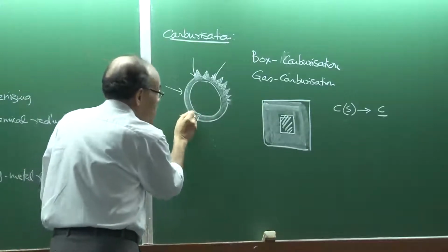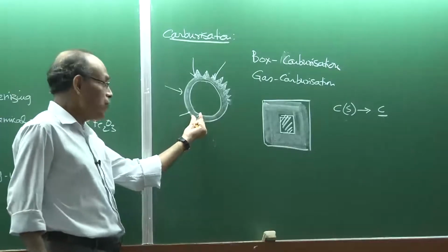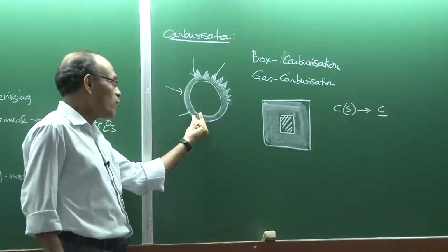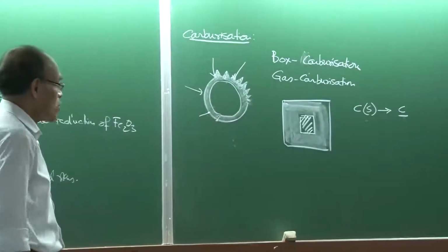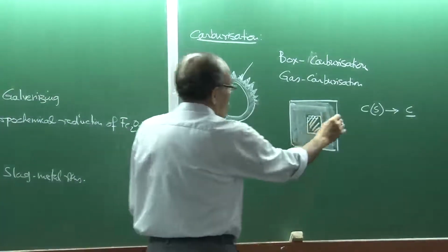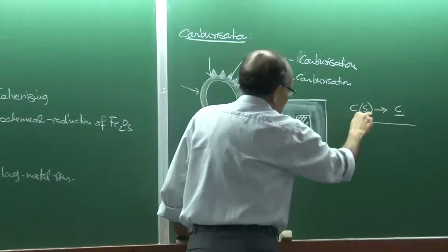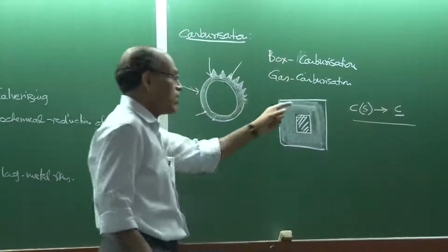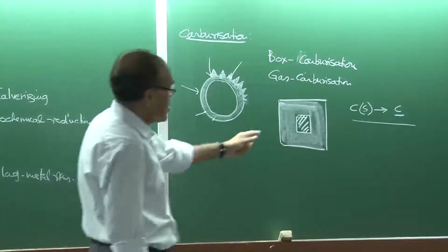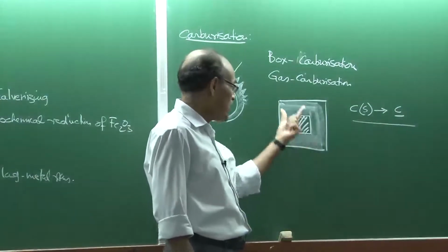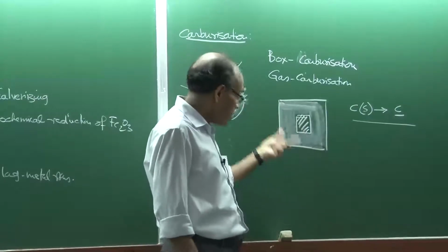Okay? Then the diffusion process comes, and it is said that the rate of growth of the carburized layer is equal to the rate of carbon diffusion. So the chemical reaction is not the rate-limiting step; this reaction is at equilibrium. So we can find out the surface concentration by invoking the assumption of equilibrium. The reaction takes place in a sealed environment, there is no oxygen there basically, okay? So therefore carbon, as the temperature increases,